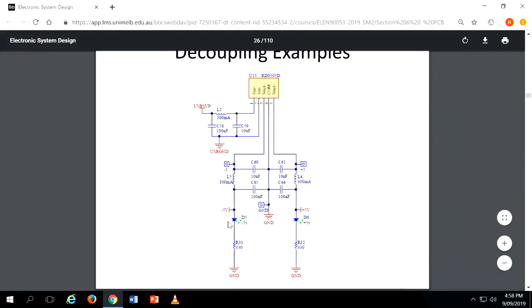So this is one way of doing it. You don't need this LED, but if you want, you can put an LED here so that when the power supply is on, the LED is lighting, meaning the -5 is definitely going. Maybe another color for the +5, so that you know the +5 is definitely going, something like that. So this is an example, where you can see this part is connecting to your IC. Then you can see here, this is your big tantalum capacitor. So this is your local source. It is not drawing from this one, it is locally drawing from here.